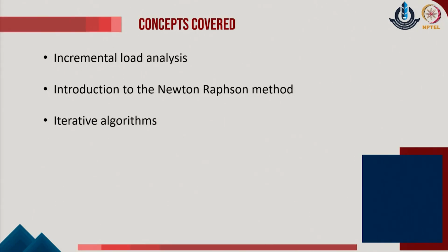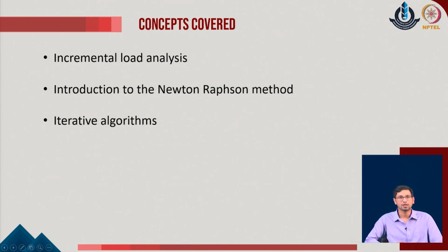We have formulated the geometrically nonlinear problem for the standard beam cases in the last session. Now moving ahead with this lecture, we would like to see the standard analysis approach for these given problems. So we will try to see what the incremental load analysis is, and what challenges we regularly face in these kinds of problems. Then we will also come up with the correction or the iterative approaches, which is one of the standard approaches like the Newton-Raphson method, and then we will see how these corrections can improve the overall estimates in these nonlinear analysis cases.